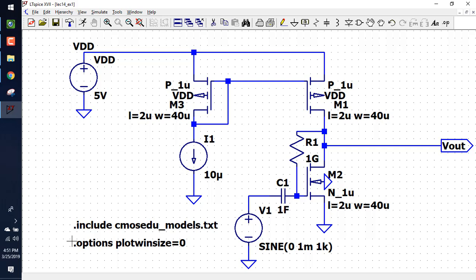So on this Pro, if people that have had 421, 621, you see here where it gets everything, right? And you notice in 421, 621, when you use Cadence, commercial software, it doesn't. You have to actually tell it what you want. If you don't say, I want this, it won't save it, because if you're doing a billion transistor circuit, it's just not reasonable to save everything. So it simulates and then saves what you want, and then that's it.